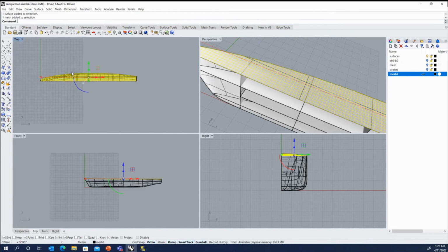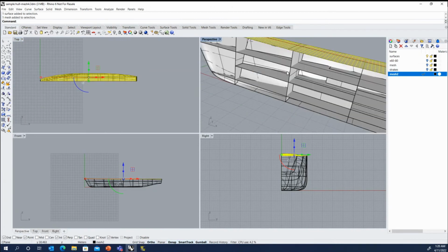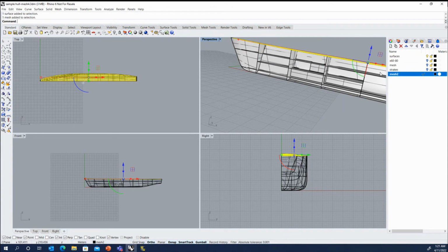And having that constant girth can come in handy when you are creating the shell stringers along the length of the hull. As long as all of your transverse section cuts there are pointed upward, assuming you want to start your spacing from the deck moving up, as it marches forward, it'll add an additional stringer as the girth increases.